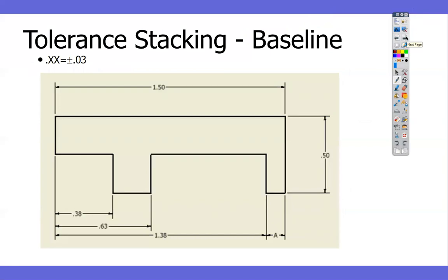All right. Here's the hard part. So what's baseline dimensions? We just talked about it like half an hour ago. How long something is? It's going to start from one point all the way across. Yeah, all the measurements start from the same thing and go across, right? So here's this part. I have an overall dimension here. I have a dimension from this side to here, the side to here, the side to here. And then this part right here, there's no dimension, right? So if I had this dimension, that'd be too many dimensions.